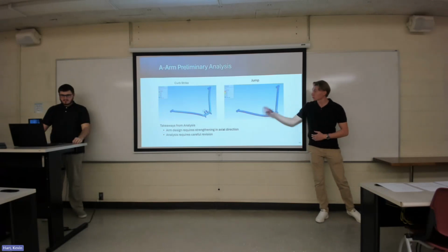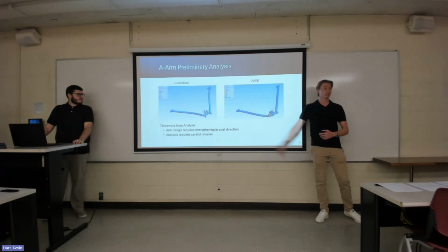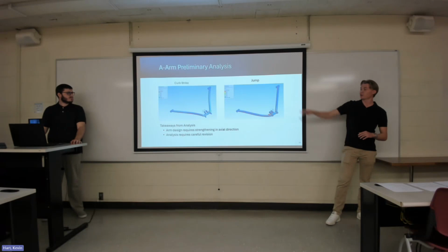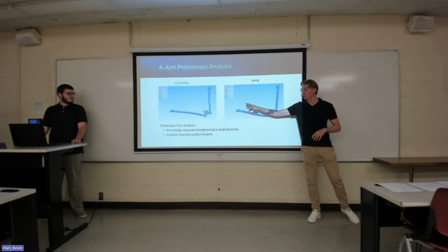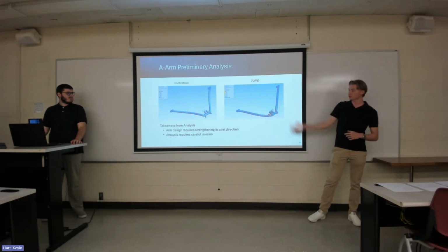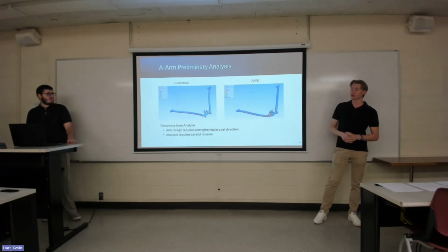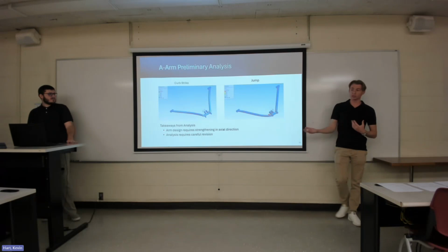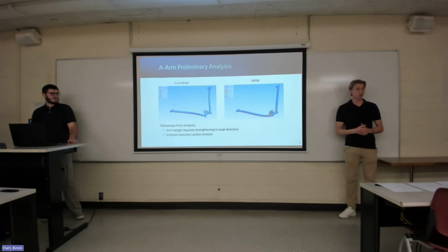For our curb strike load case especially, we have 150,000 PSI of stress in that small weld region, where the rest of the part is faring just fine. That's one area where I believe that load case would benefit from some refinement.